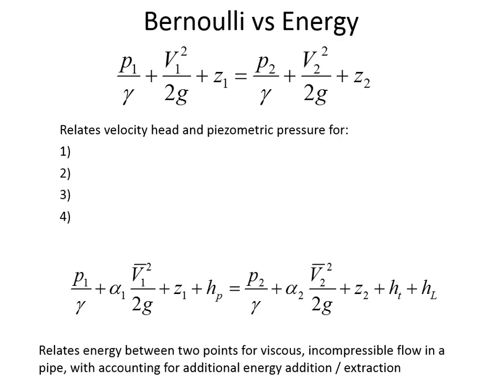So this profile means that when we square the velocity at a certain location, we're going to be coming up with a mathematical error that has to do with the fact that the velocity up here is much greater than the velocity down here, and when you account for the average velocity, you need to boost the overall factor up a little bit because some of the velocity at the center of the pipe was higher than we really gave it credit for.